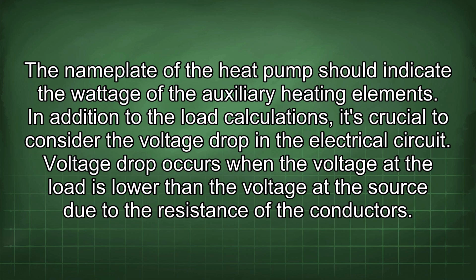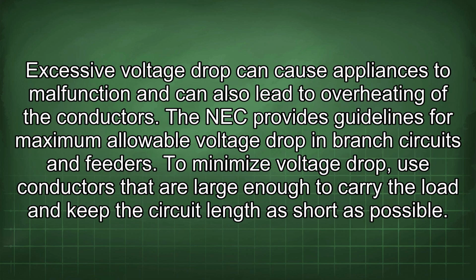In addition to the load calculations, it's crucial to consider the voltage drop in the electrical circuit. Voltage drop occurs when the voltage at the load is lower than the voltage of the source due to the resistance of the conductors. Excessive voltage drop can cause appliances to malfunction and can also lead to overheating of the conductors. The NEC provides guidelines for maximum allowable voltage drop in branch circuits and feeders.